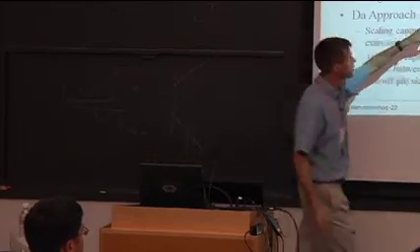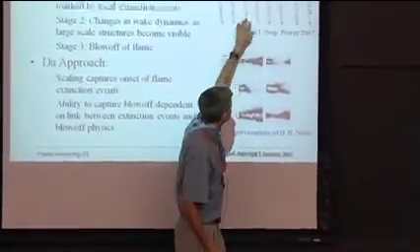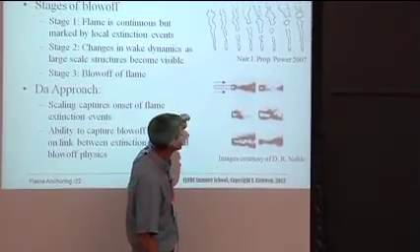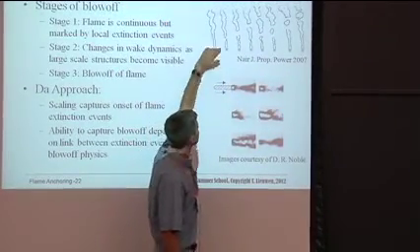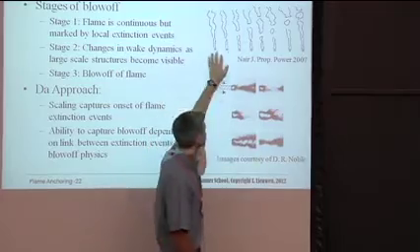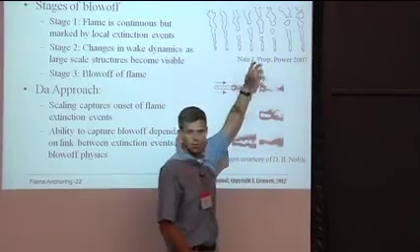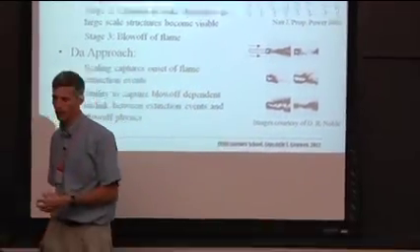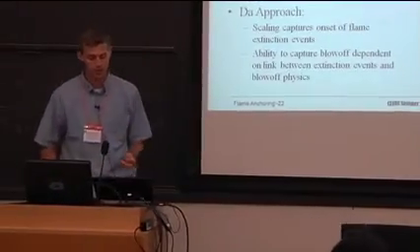So in other words, here I got a couple holes in the flame, but no big deal. If I keep dropping the fuel-air ratio, what will happen is more and more of the flame downstream will be extinguished, but it will still hang on in the near field because as long as it's being piloted, it can't go out. The flame does not extinguish.